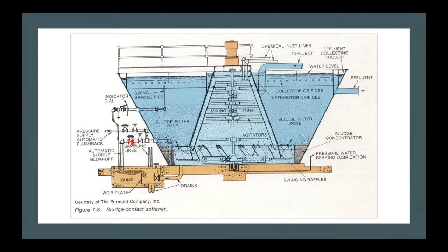This has another feature too. So I've got a blow-off valve that opens up intermittently and discharges sludge. But after it opens, we're going to have this line that's all full of sludge, and the sludge is going to settle inside of the pipe and plug it off. So every time after this blowdown valve operates, immediately afterwards, a backflush valve is going to open up and put pressurized water through to clean out the line. Very, very common. And if you work in a SAGD plant, you'll see that.